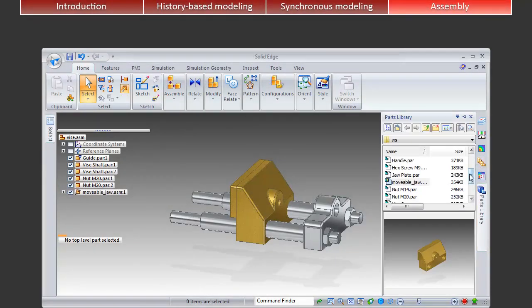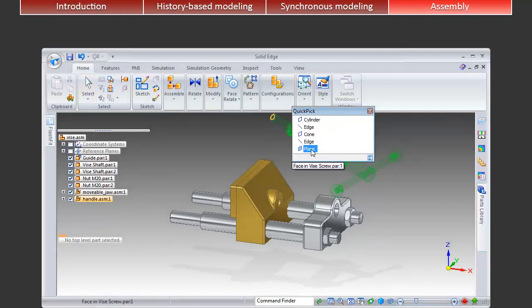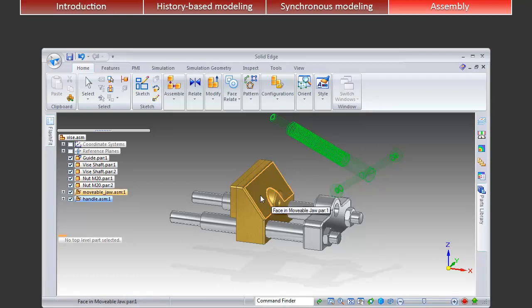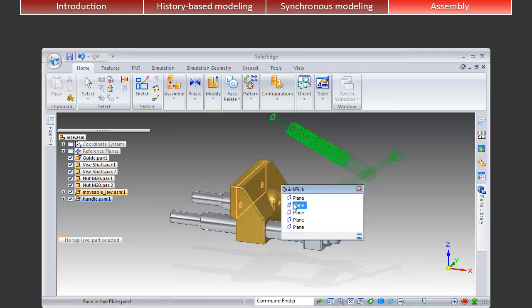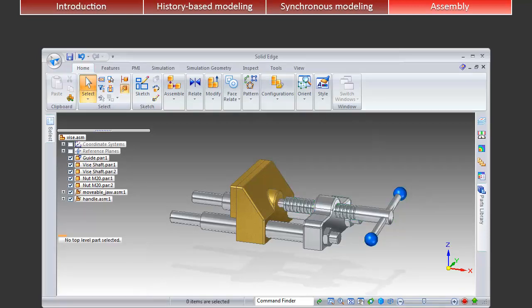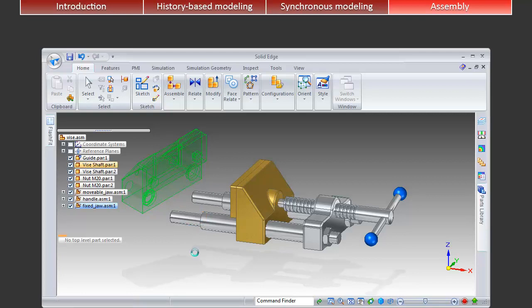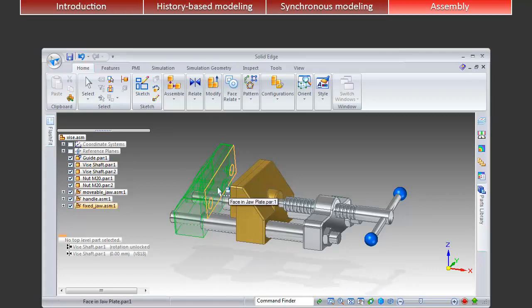FlashFit uses different geometry types to quickly apply planar align, axial align and mate relationships. A planar align relationship positions components with planar faces aligned in the same direction. Axial align relationships align components along the linear axis, like a shaft and a hole. A mate relationship positions components with faces towards each other. More relationships, such as cam, connect, tangent, and angle, provide a robust set of relationships to define assembly structures.